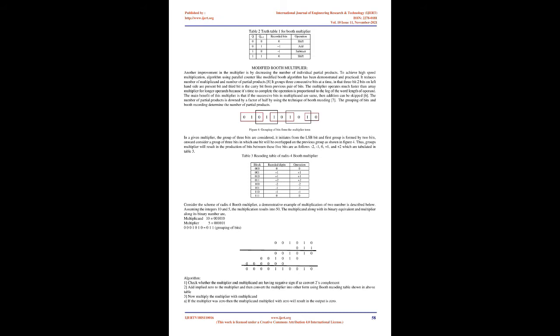A 4-bit adder is used for implementing CSA. The carry output from the first addition is the carry input in the second addition. The advantage of CSA is to increase the maximum frequency. The Wallace tree multiplier using CSA occupies the smallest area. In the Wallace tree method, due to irregular structure, layouting the circuit becomes more complex although the speed of the operation is high, since the circuit has an irregular structure.